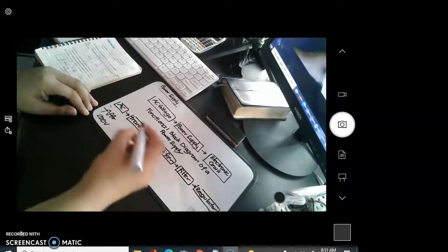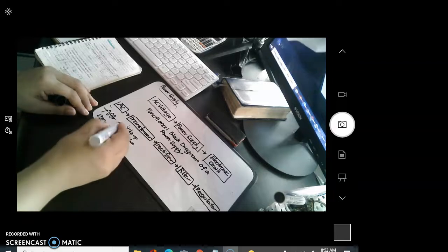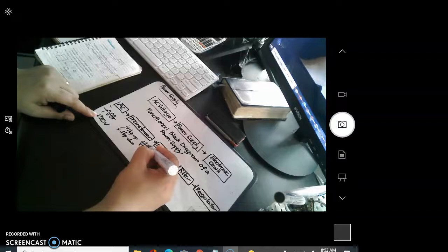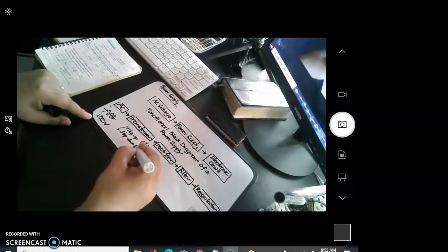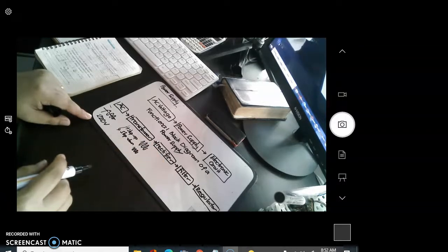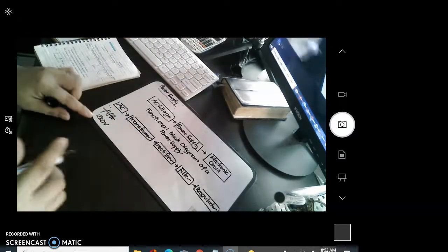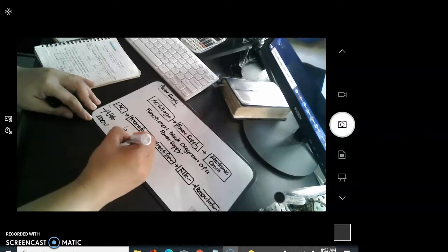The step-down transformer. As you recall, we have what is known as the step-up transformer, and we also have a step-down transformer. Alright? So for the step-up transformer, from 220 volts, it will increase the voltages. For a step-down transformer, the 220 volts can now be stepped down as low as 12 volts, as low as 9 volts. So in the case of the power supply, what we are going to use is the step-down transformer. So meaning to say, from 220 volts, for sample purposes, we can apply a step down to 9 volts or 12 volts.